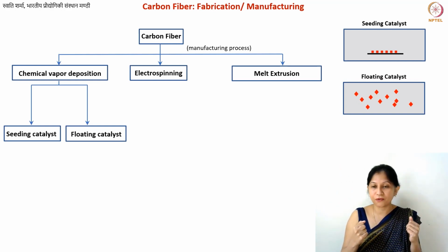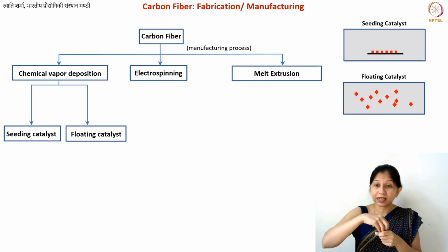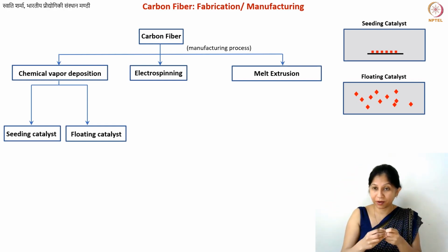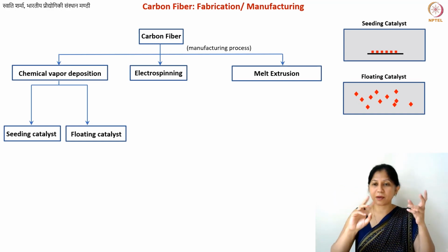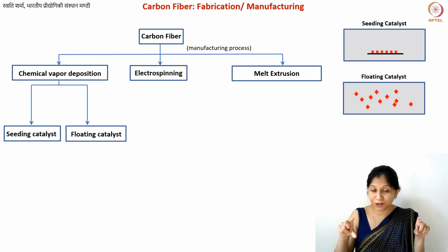Of course, in the case of seeding catalyst, there is also something very interesting. What is the mechanism? The catalyst particles, after the fabrication of the fiber, does it stay on top of the fiber or at the bottom of the fiber? In fact, both of these are acceptable mechanisms, and we'll discuss them more in the context of carbon nanotubes as well. But in the case of floating catalyst, this then doesn't matter, because all of your fibers are floating anyway. Also, these fibers, where do they go? They typically deposit on the walls of your tube.